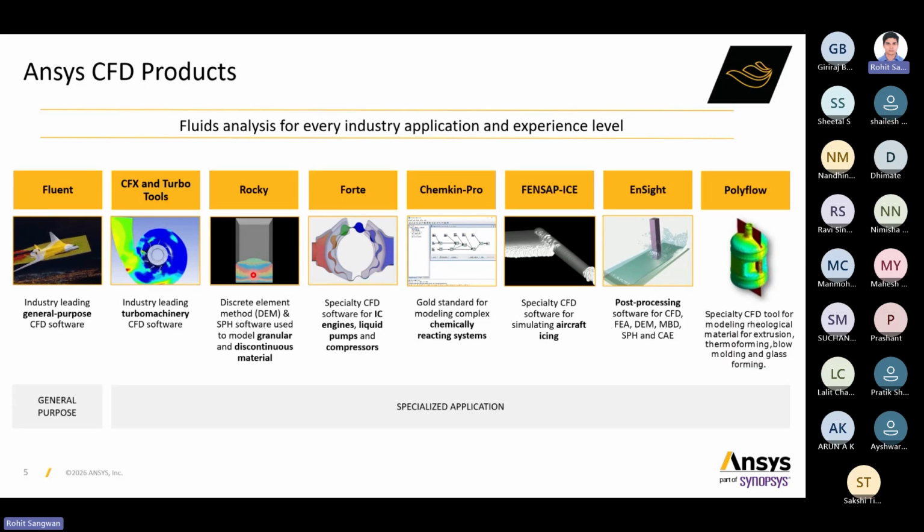Rocky is a tool where we study particle behavior, how the particles move or interact with the fluid. You can take the example of coal mining. When I'm breaking coal and transferring it through a conveyor belt, in what size should I break it, how will I transfer it through wagon wheels, and in what quantity or at what speed should I fill that coal? So I can study the particle forces and the particle movement. We study all of these inside Rocky.